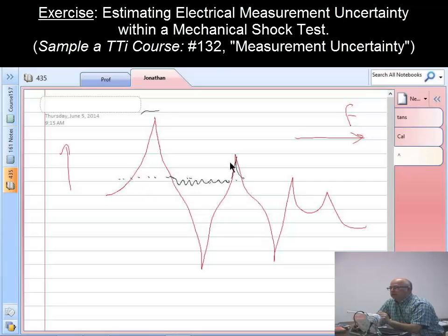When we got to about 10-bit A to D converters and we thought that the world was wonderful, at that stage we'd get down with the dynamic range and the signal would come down and we'd lose the anti-resonance. Sometimes, it depends, but essentially we'd lose the real low points. These days, most A to D converters in quality equipment are at least 12 bits, and at that stage the dynamic range is such that we get the whole signal. And if the resolution of a 12-bit A to D converter is causing the problem, then there's something else going wrong with the test.